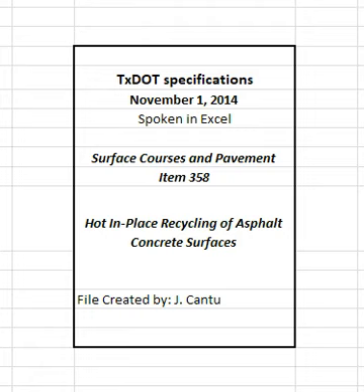4.11 Weather conditions. Unless otherwise approved, perform hot in-place recycling operations when the existing pavement surface temperature is 60°F or higher and when weather conditions and moisture conditions of the roadway surface are suitable, in the opinion of the engineer. Measure the roadway surface temperature with a handheld infrared thermometer. The engineer may allow mixture placement to begin before the roadway surface reaches the required temperature, if conditions are such that the roadway surface will reach the required temperature within 2 hours of beginning placement operations.